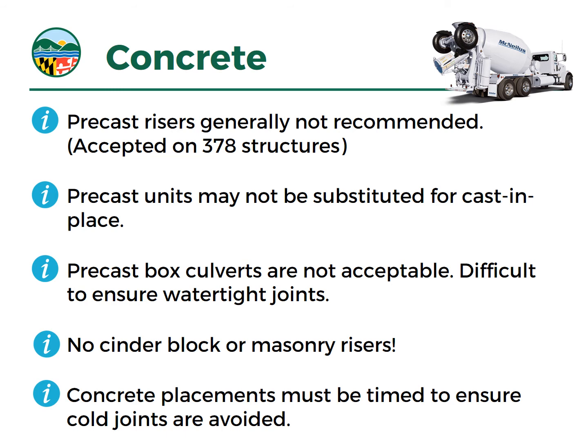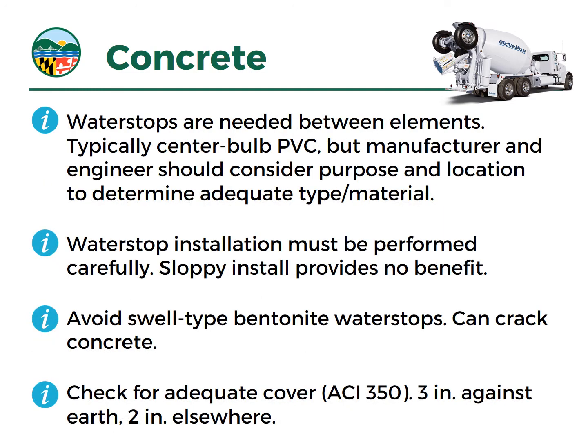If somehow that slipped through or the contractor is proposing a change in the field, that should be rejected right away. Concrete placements should be timed to ensure cold joints are avoided. That's just general good concrete practice, but cold joints are another area where you could get seepage and soil loss and other erosion problems in your concrete.